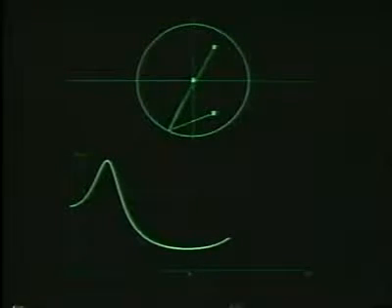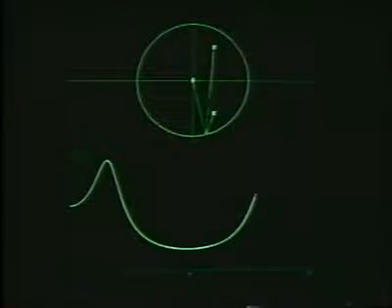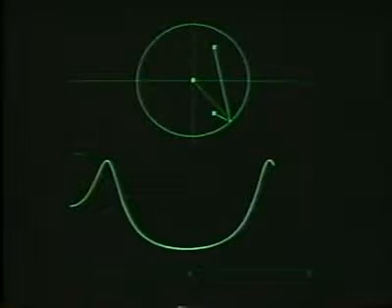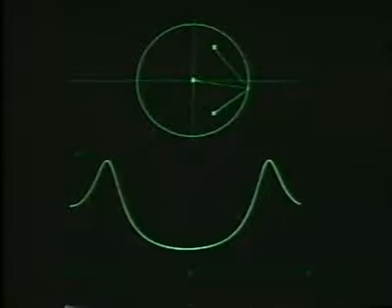And so, in fact, that corresponds to generating a resonance as we sweep past that pole location as we are here. And then finally, that pole vector increases in length as we begin to approach omega equal to 2 pi, or equivalently as we approach omega equal to 0.